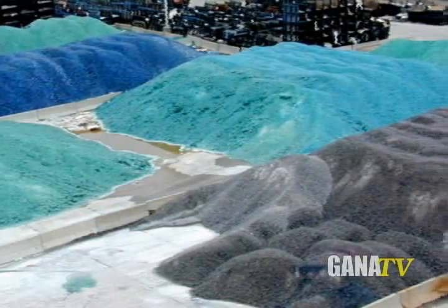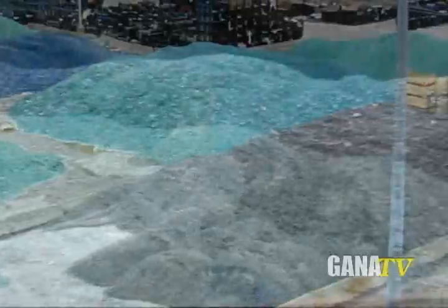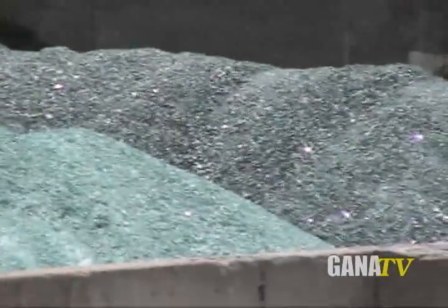Glass itself is also an important ingredient. Broken glass, called cullet, is added to the batch. Cullet is recycled from the manufacturing process and also accelerates the melting of the batch while reducing the energy required for melting. After a thorough check to ensure the integrity of the batch, it's fed into the filling end of the furnace automatically.